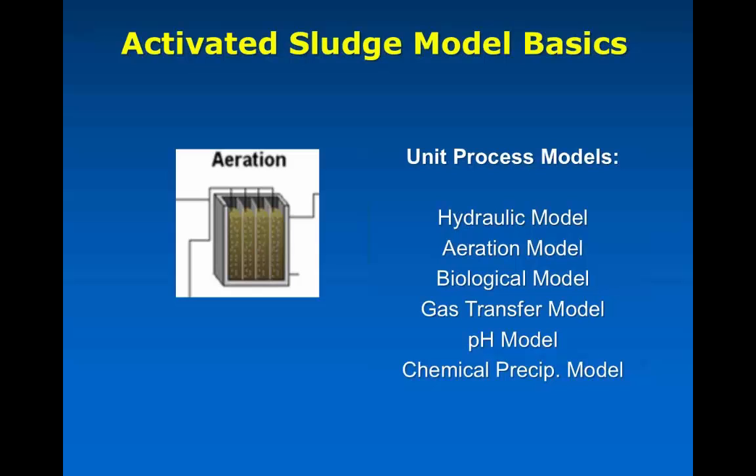Okay, so on to the more complex models have gas transfer. So for parts of GPSX where we have the more advanced libraries, and we're keeping track of things like the generation of methane, our carbon footprint and greenhouse gas library has even more things that are included in those calculations. Those are all parts of the model that are there so that you can get an estimate of the loss of gases to the atmosphere and so on.